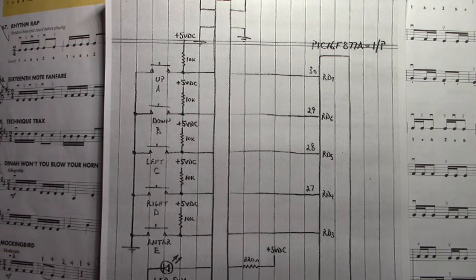So we saw how to program, how to set up the pulses per revolution, whether it's going to be Hall effect or encoder output on P5 or P6, P5 being the Hall effect, P6 being the encoder output, and whether it's going to be open collector or differential output, and at what point the Z pulse for the encoder output fires, whether leading edge of A, leading edge of B, trailing edge of A, trailing edge of B. And we saw the home pulse width that we could change, either very narrow or very wide.